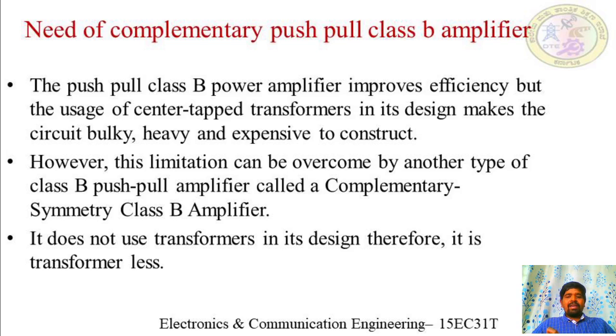But for the time being, I can say that class B push-pull amplifier efficiency will be high, but the center tap transformer will make that circuit costly, bulky and heavy to construct. So that's why, to overcome this limitation, class B push-pull amplifiers can be made into complementary symmetry class B amplifier.